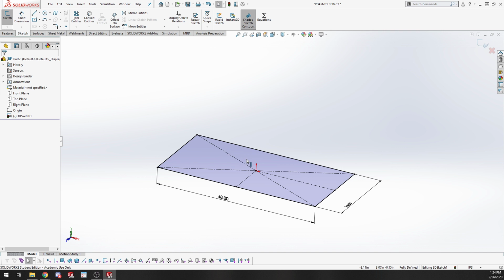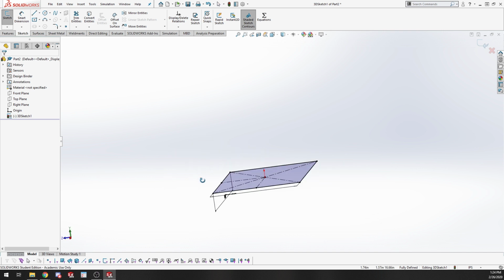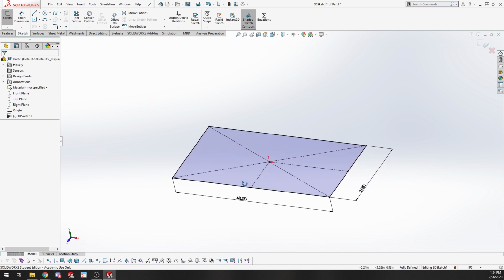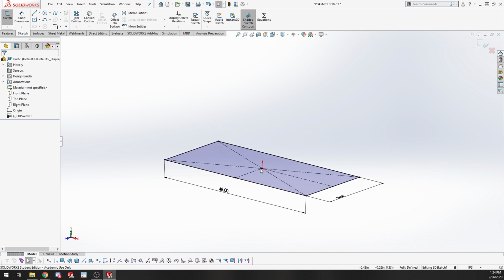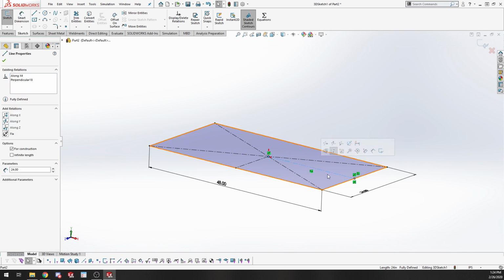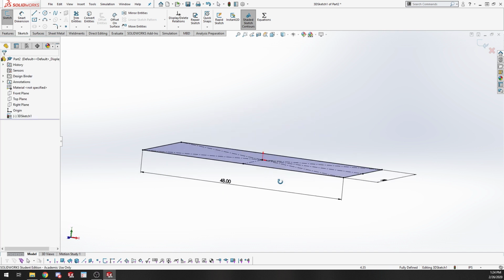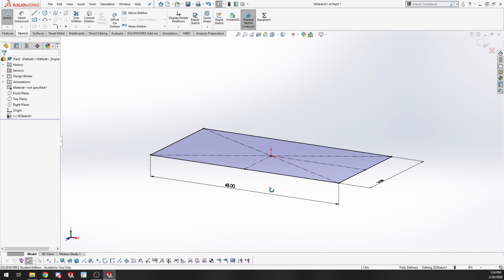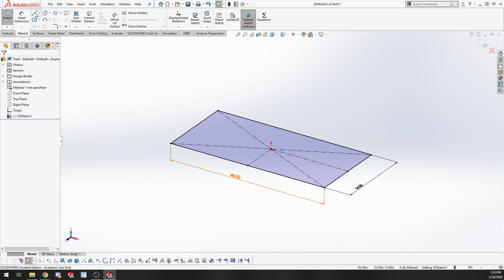All right. So SolidWorks, what it was doing there was everything was still underdefined because it could rotate around. One thing that I should add is that everything gets based off of this origin. So that's kind of why it was spinning around like that. I really have to start off from the origin and kind of make this line be along that x-axis and kind of define from there. And same thing with this along the y. It doesn't really add those on-plane relations that it would with a normal sketch. So now we have a base to start off with.